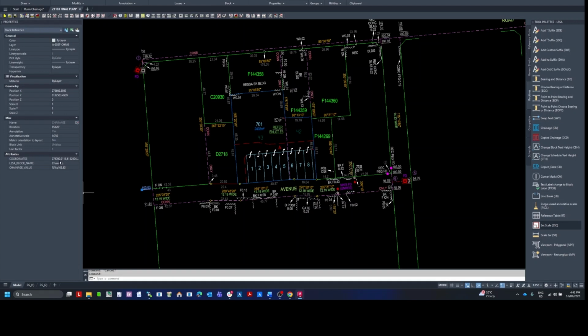It's also important to have the coordinates listed under the attributes, and those coordinates relate to the vertex along a line that you are trying to reference with that distance. As I said, chainages must refer to a vertex along a line, otherwise the polygons can show with missing dimensions.